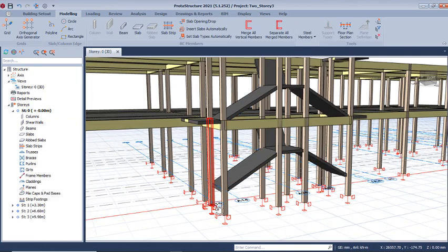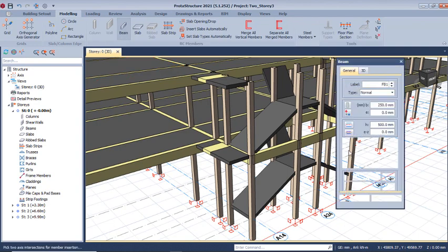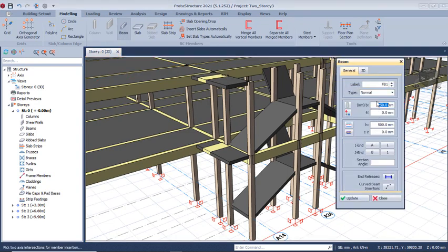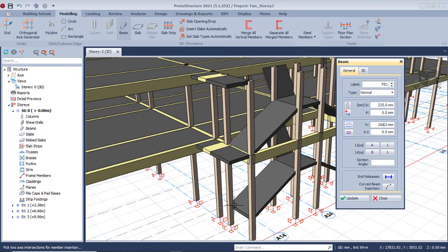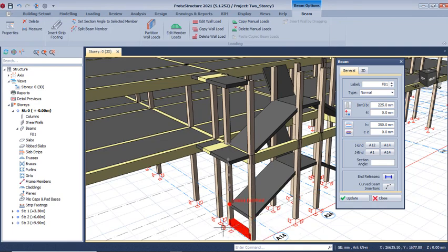At this point we'll be having a beam. It's going to be more like a ground beam. So click on the beams, then you have the beam to be 225 by width, and the depth you can have it to be 350 right there. After which you place it from this point to this point, so it goes down direct to the floor. So you need to take it up.